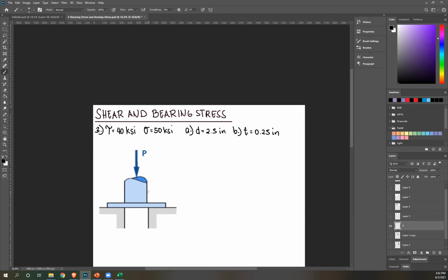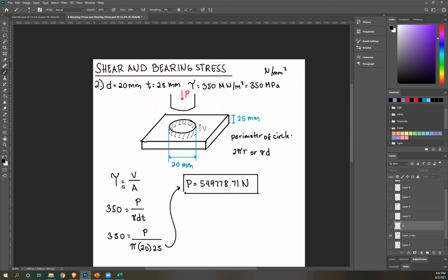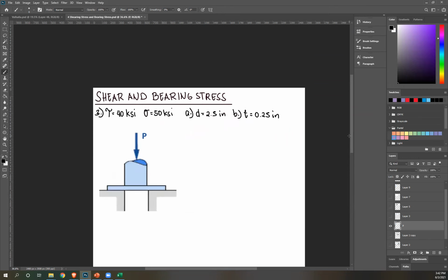But unlike our previous drawing, this punch doesn't have any limitation, so that's why we directly solved for shear. Whatever force P is on your punch, that is the shear force of your plate. But now it's different. We have a limitation on that, so we're going to start with that.